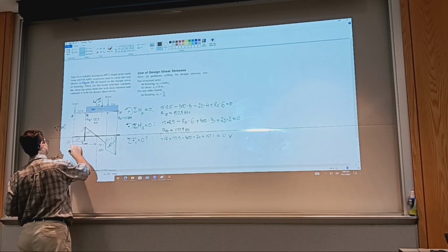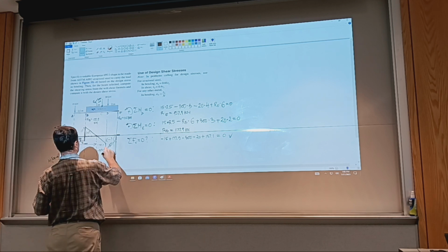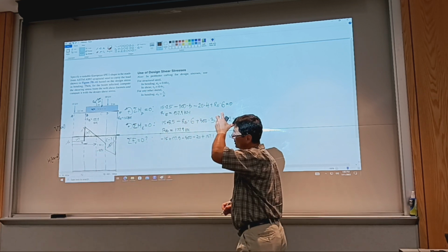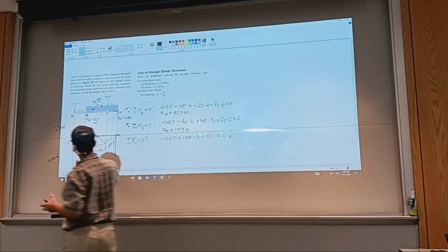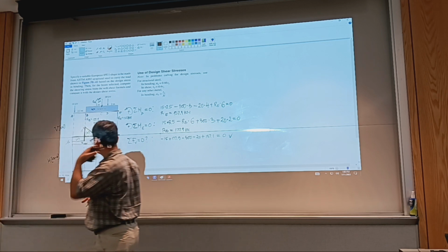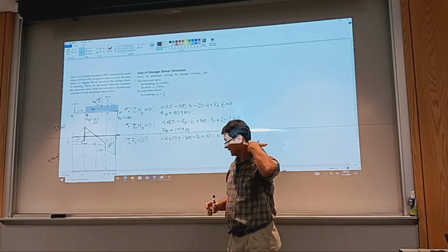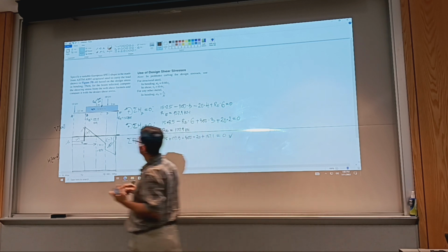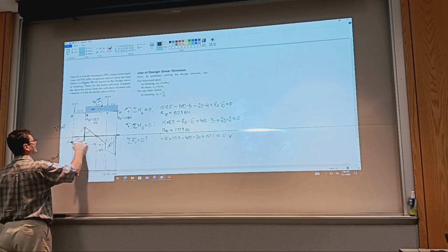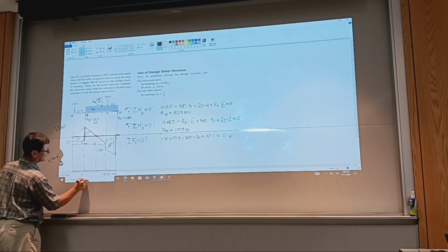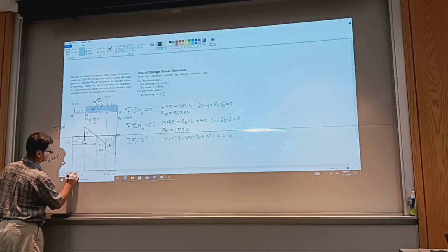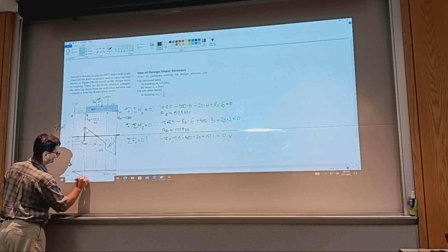So on the moment diagram, I'm going to see things happening at the 4. So moment begins at 0 and goes with a negative slope. Right, so this is a linear moment. I have a constant V, linear moment. So I go linear, slope of negative 15, from 0 again to point B.